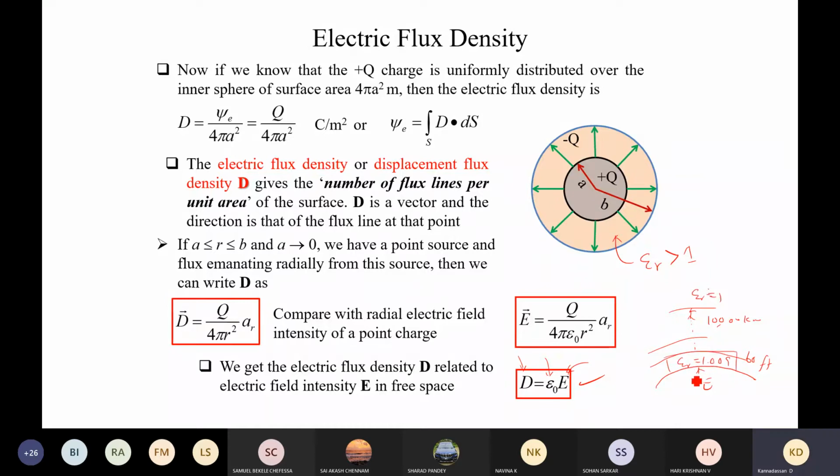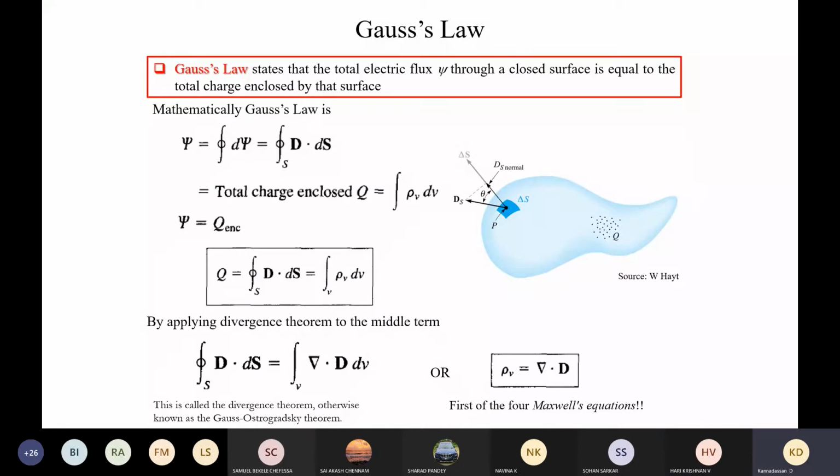This means that our air medium is exaggerating the field distribution, and by the way, we get denser flux lines. So the medium defines the properties of the flux density. This is a minor difference between the flux density and the electric field. And the Gauss law is again a very useful one to describe the flux density, thereby we can easily calculate the electric field. While Coulomb's law goes from charge to electric field, the Gauss law, in the opposite way, can give the electric field to charge density.